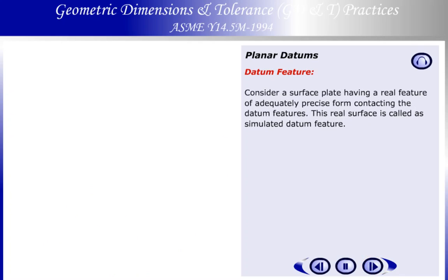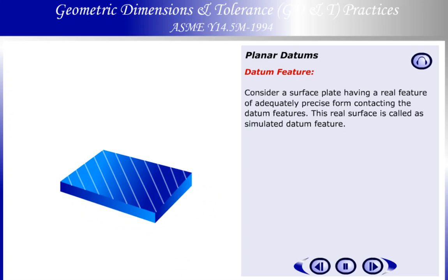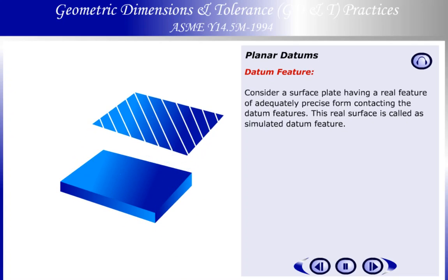Datum feature. Consider a surface plate having a real feature of adequately precise form contacting the datum features. This real surface is called a simulated datum feature.